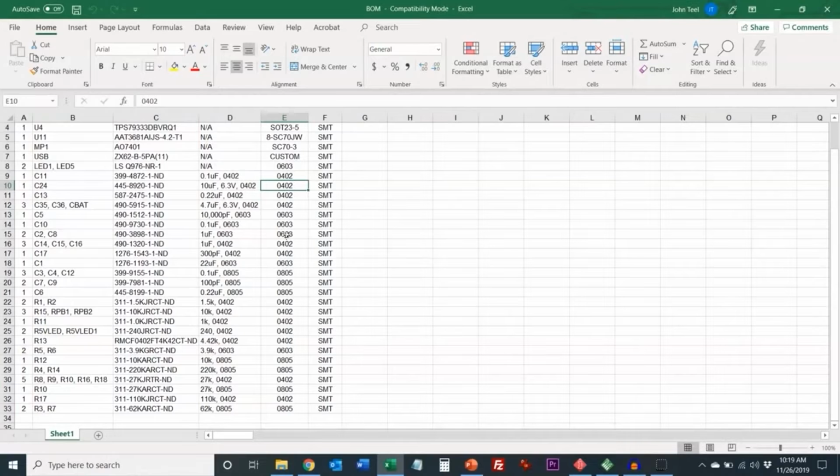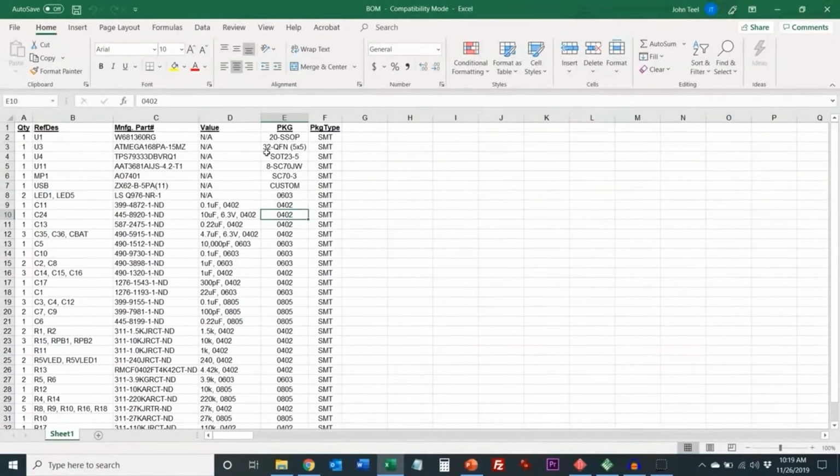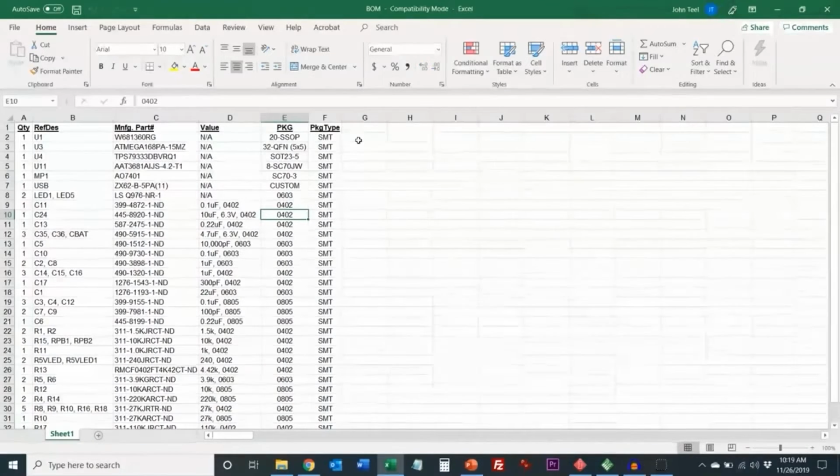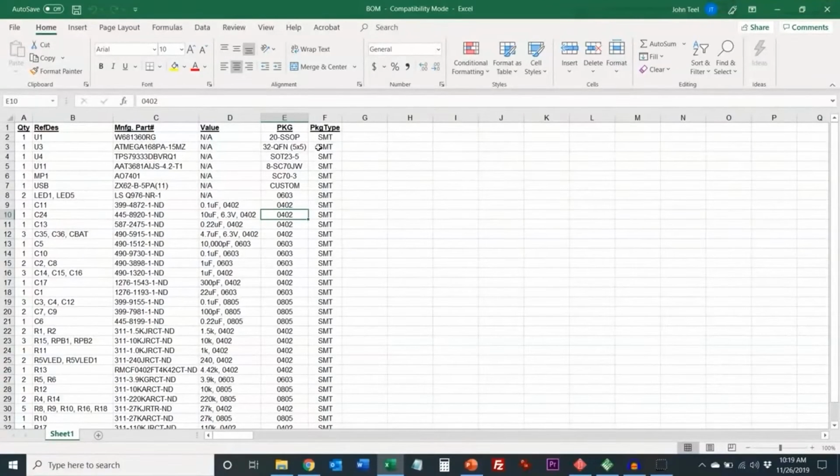One thing I don't show in here is the price for each of these. So if you're wanting to use your BOM to estimate more accurately or calculate your exact cost for your electronic components, then you could also just include the price of each of these components here, or have that in a separate document, since the pricing isn't really something you necessarily want to or need to send to your manufacturer. You could keep that in a separate BOM that just includes the pricing. This BOM just has the information that you send to the manufacturer.